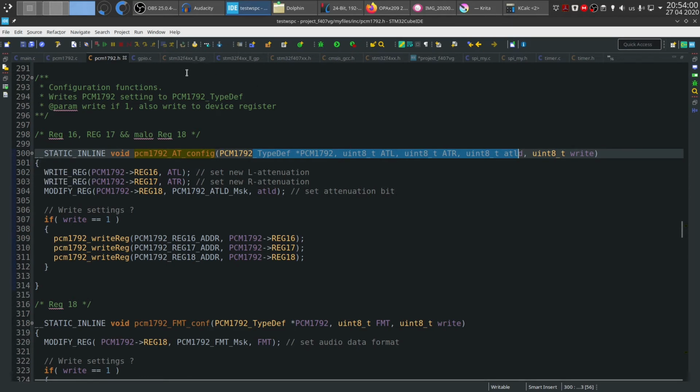So static inline in the header file. The C file will only store functions that will also be available to other functions. So some kind of init function, start, stop function, maybe some kind of mute functions that I showed you before. So this is a kind of function that I want other functions to be able to use. But this one, like the atconfig, is really going to be used only by the functions in this particular .h and .c files. So it's going to be local, so there's no problem having them as static inline. And I'm going to show you where these functions are used.